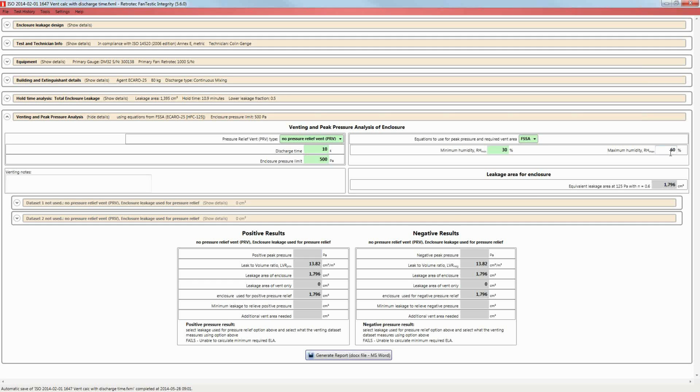humidity meters can be relatively inexpensive. You can get one for about 25 bucks or so. So, you know, when you're going from installation to installation, you can just have it with you and get a sense for the humidities that different enclosures would be run at. And sometimes there will actually be a design specification for a computer room that they will be maintaining humidities within a narrow range. So it's up to you to find out what that range is.